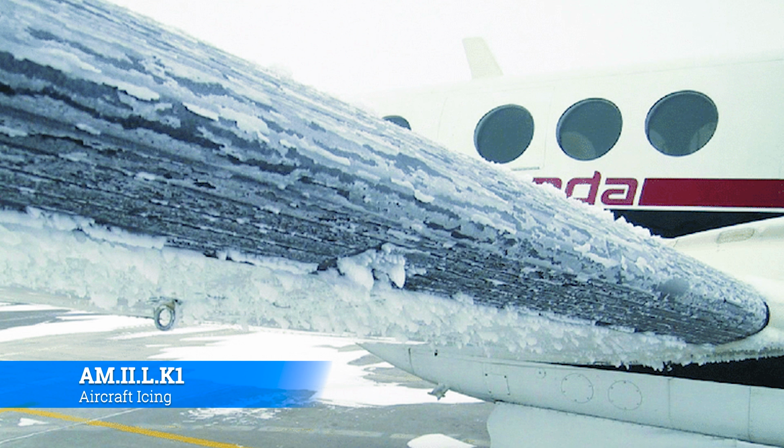Leading edges of anything, be that the wing, the horizontal or vertical stab, the engine cowlings, whatever, are always very, very susceptible to ice. And most of the time, on your more mature aircraft, you're going to have anti-ice systems built into it to basically prevent this exact thing from happening. So you can imagine the lift getting spoiled on this particular airplane as the air tries to travel over the top. But pay attention to leading edges for ice.